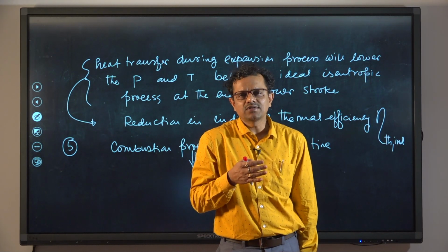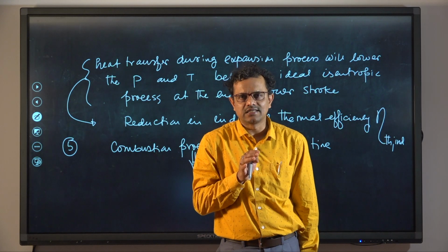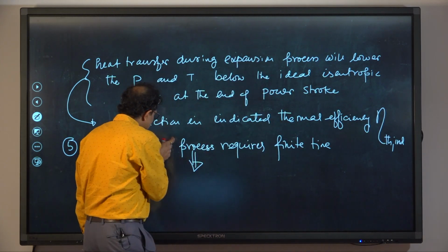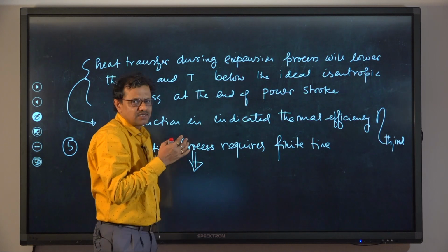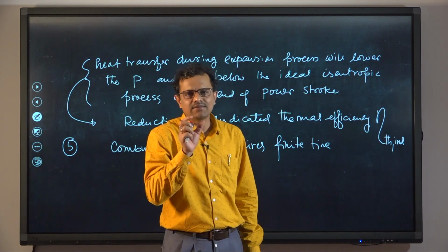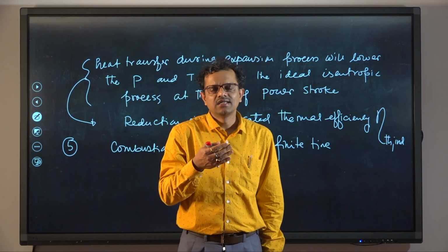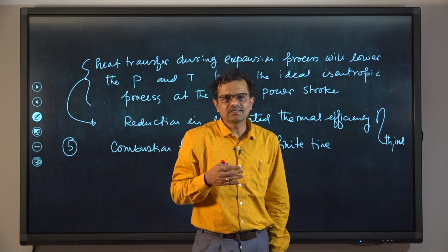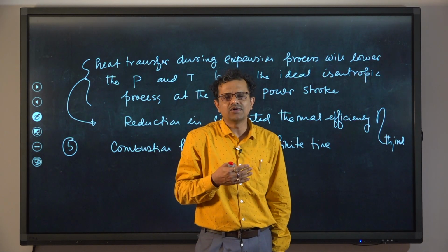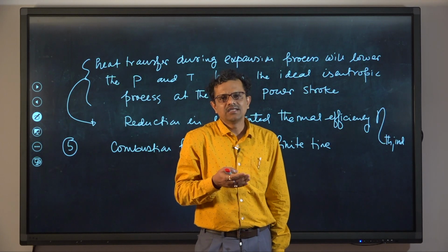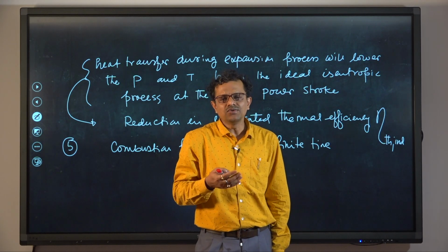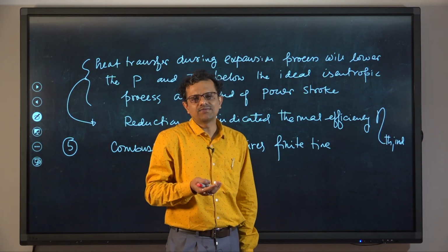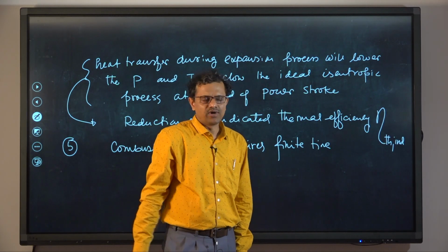it is really not possible to transfer heat instantaneously. That means, if we consider the real process wherein combustion will require a certain amount of time, as a result heat transfer will not be instantaneous, and if it is not the case, then the assumptions of constant volume or constant pressure, these two will not be true, and hence the actual cycle will certainly deviate from the ideal one.